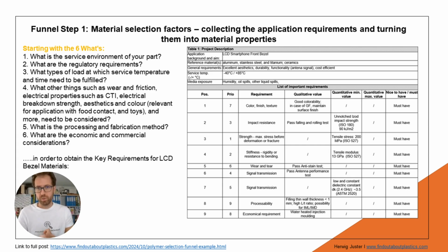Like, the first what is the service environment of your part? What are the regulatory requirements, what type of loads you expect, what other things like friction and wear, what will be the processing method, and additional fabrication methods, post-processing topics, what is the economic and commercial expectation and considerations. And there are many more questions, and I have a link to even more questions in the blog post of this example. I will link this also below.